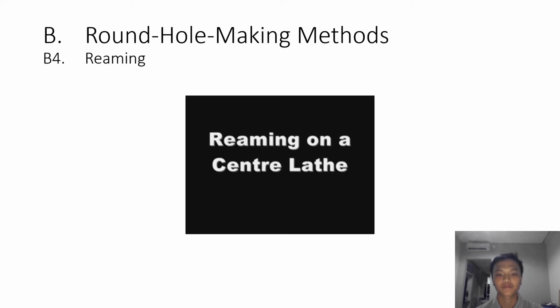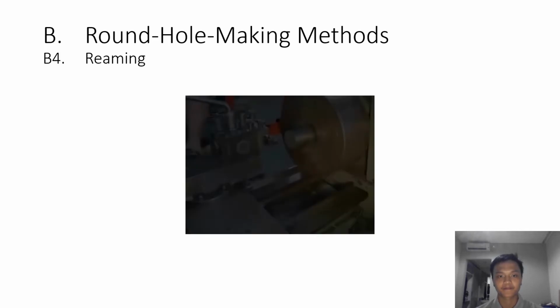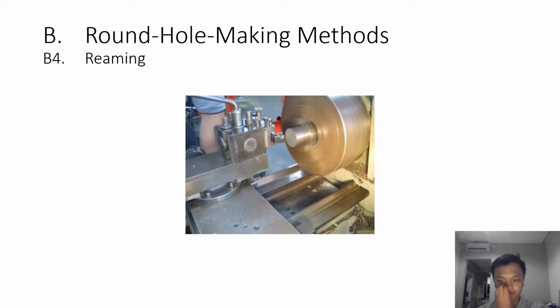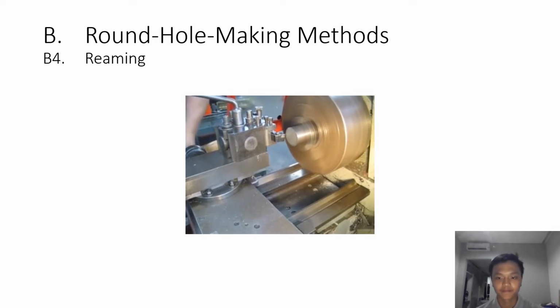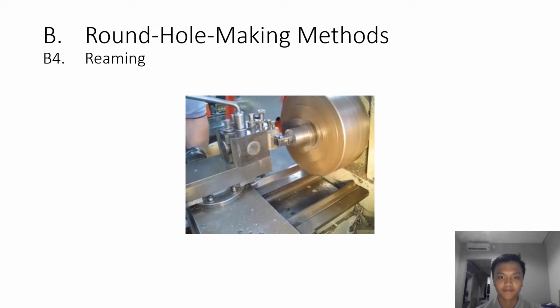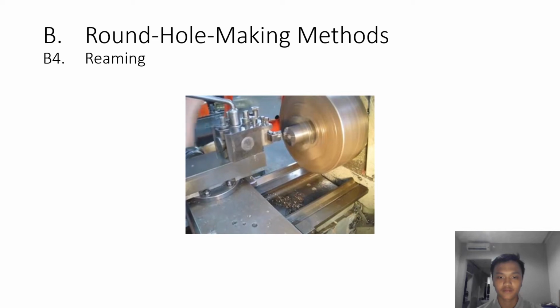Here you will see the procedure for reaming on a lathe. For the purpose of this instructional video, reaming of a 12mm diameter hole will be demonstrated. Secure the material in the chuck and set the facing tool to center height. Set the lathe for high speed. In this case, the machine is set at approximately 2000 RPM. Face the end of the material to ensure a flat surface. Note that a moderately high feed rate, approximately 0.25 millimeters per revolution, is used and no coolant is required.